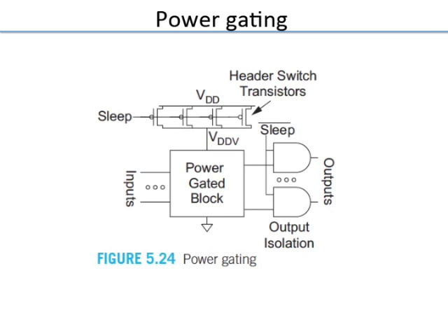So you see all these complications come in even to implement such a very simple idea. All these physical aspects have to be considered for you to be able to engineer this properly. And then of course when you shut it off and all these voltage signals go down, they are transiting down, slowly VDD is degrading. If this signal is fed to another block which is not power gated, which is still running at 1.2 volts or wherever it is, it's not good, right? Because the signals are decaying down. There will be an intermediate voltage for a long period of time. So you have to protect it.